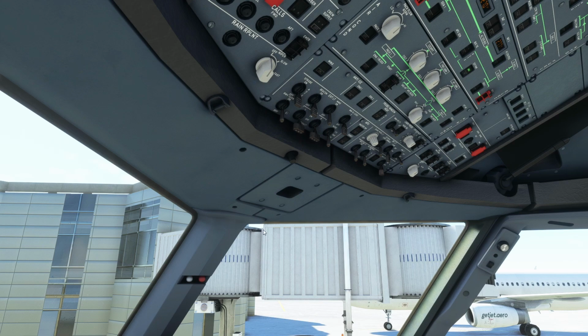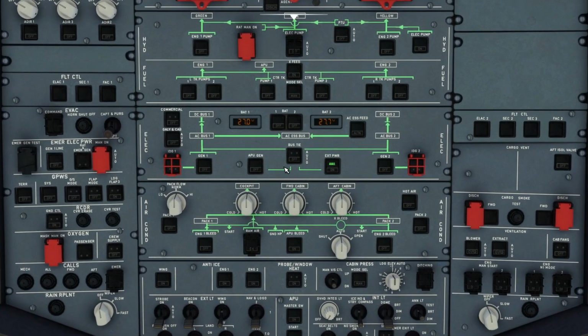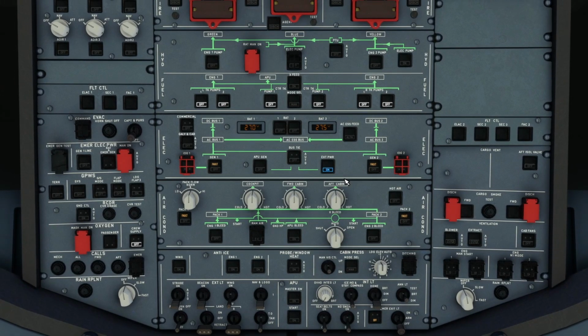With that done, we are ready to turn on the batteries. So up on the overhead panel, over here we go, battery 1 and 2 to the on position. The batteries supply very little power to the aircraft. The rest is powered by either ground power or the APU. For today at Manchester, we have ground power available, shown by the external power available light on. So let's go ahead and switch that on now. And now the rest of the aircraft has been powered up. Some airports or remote stands don't have external power available, so we would start the APU and power up the aircraft via the APU.